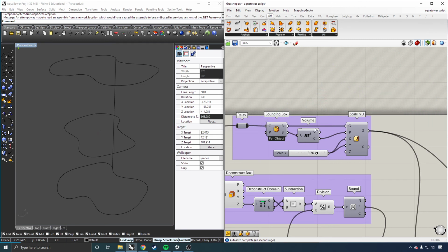But there is a difference between when you decide to use this component. Anyway, we just want the centroid, and then we want to scale things. Just like you scale things in any other program, you're going to have to say what you're scaling, which is going to be your geometry. You're going to have to say where you're starting from. In our case, there's an origin point, and then there's a base plane. We care more about the origin point, but if your plane does go in a different direction, it will change how your X, Y, and Z work.